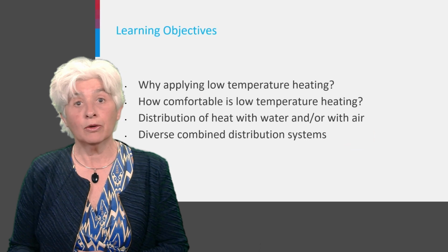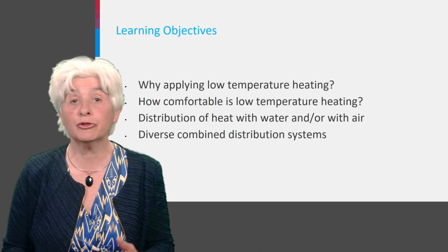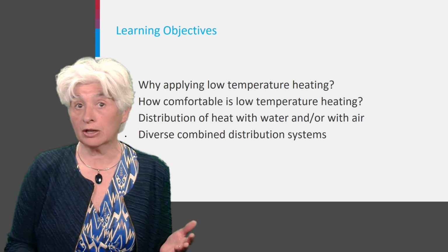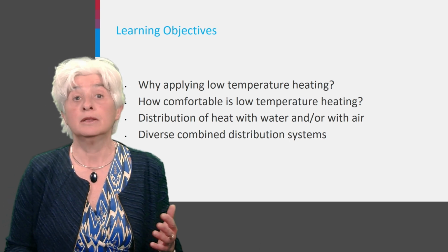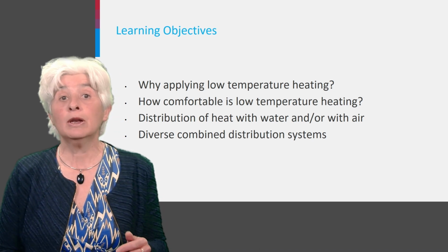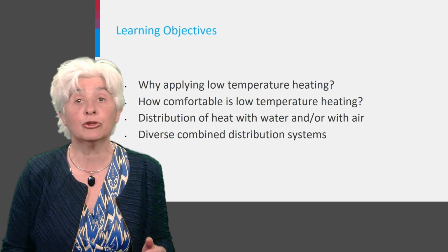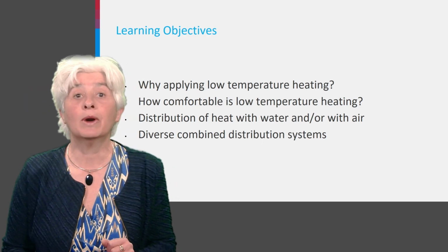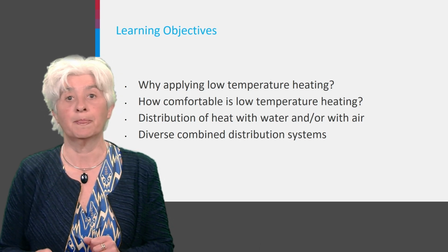To do so, you are going to discover the main parameters of distribution systems relating to the most important choices to be made when designing them. After this lecture, you will be able to make the right choice of distribution temperature, depending on sustainability aims and occupant comfort. You will also be able to make an appropriate choice of the heat distribution medium, water or air. And finally, you will be aware of the different possible combinations of distribution systems.